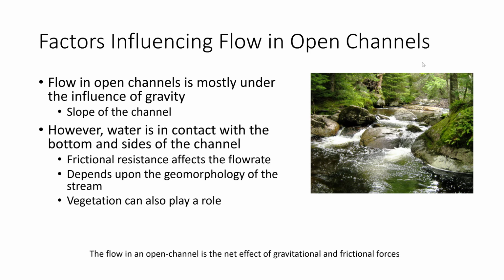So what factors affect flow through open channels? As I said, the flow in open channels is mostly under the influence of gravity. So the slope of the channel plays a big role. Clearly, the steeper the slope, the faster the water would flow. However, this water is in contact with the bottom and the sides of the channel. So there is frictional resistance to the flow that's offered by the bottom and the sides where the water comes into contact with the channel.